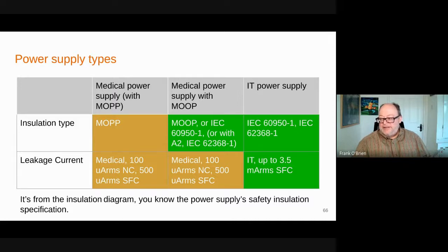And then I've got my computer power supply. They would comply with 61010 as well. It's going to meet the computer-related leakage and the computer-related insulation. And then we saw 4.6 would allow us to use that insulation in our MOOC situation. And yet we have to have medical leakage.